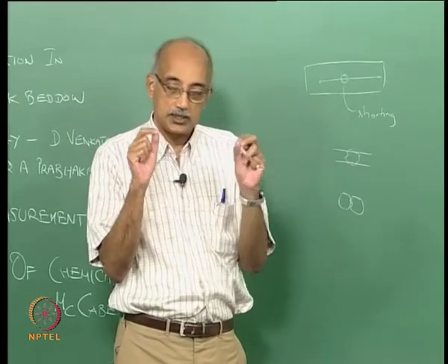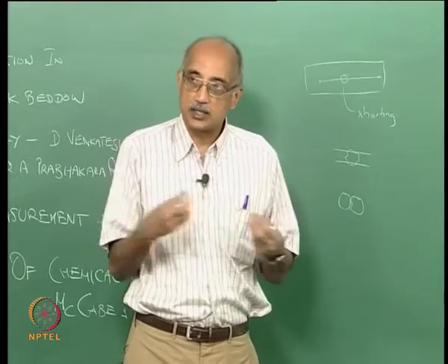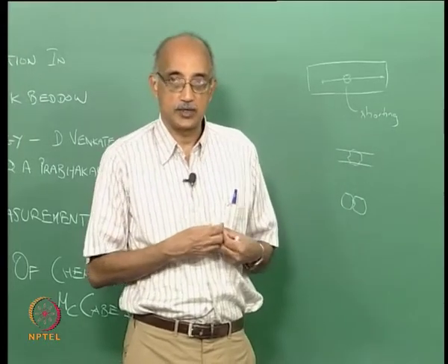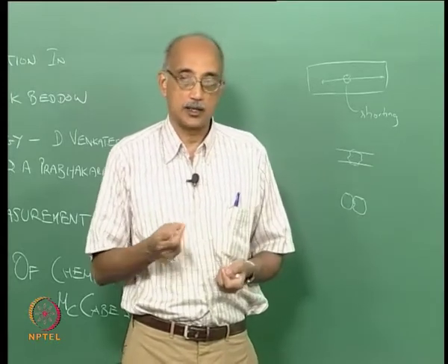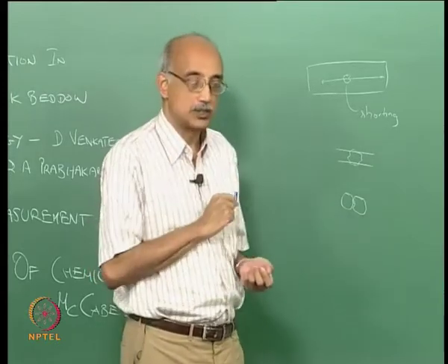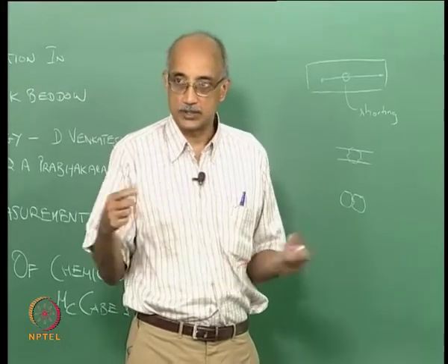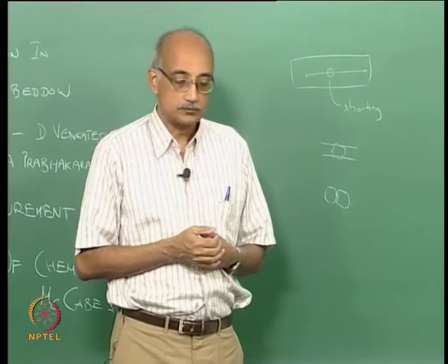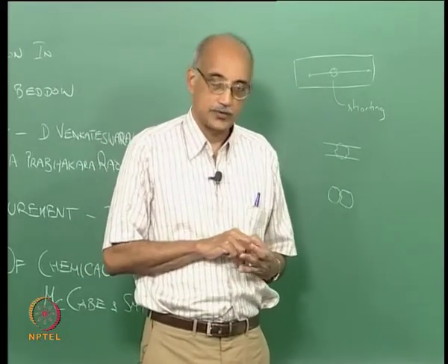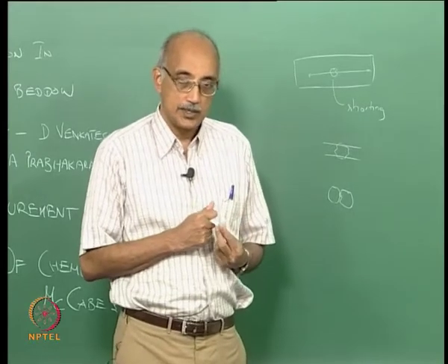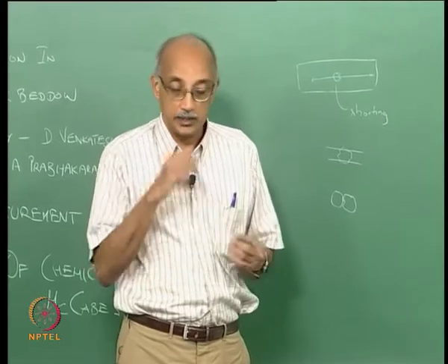When particles are discrete, the suspension acts like a Newtonian fluid. When the particles start coagulating, it starts to behave like a non-Newtonian fluid. So there's a tremendous difference in the flowability characteristics of any suspension depending on whether the particles stay isolated or whether they start conglomerating. So clearly adhesion of particles to surfaces and to each other is of huge practical significance and it's worth studying it in more detail.